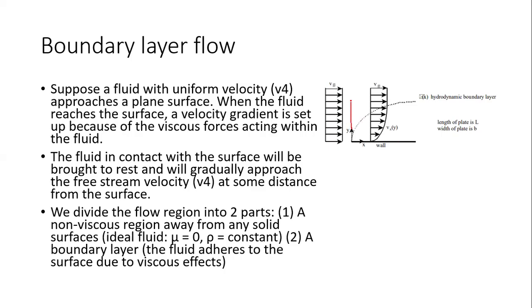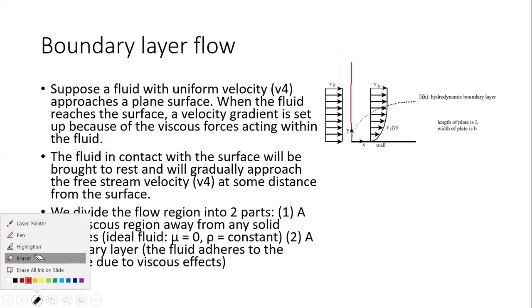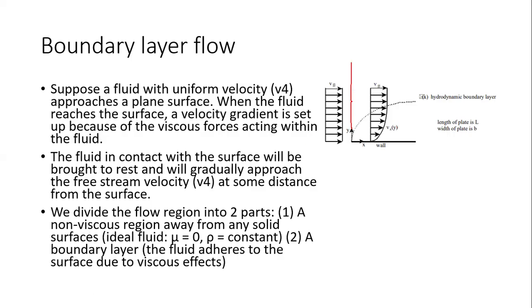We also did this illustration. So everything here, this entire area, right, is the fluid. And what we were saying yesterday was that the fluid has a certain velocity that it is moving with. So over here, the velocity is fixed. It's one velocity, right? Every layer has its velocity. But then it gets to a point where, when it touches this line, the effect of the layer below can now be seen or felt. Is that okay? So the layer below is going to slow down, or retard, the layer above. That layer is also going to retard the layer above it. Is that okay? So if one layer is retarded more, it gets to a point where it can also retard other layers more.